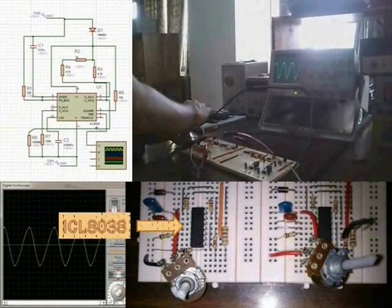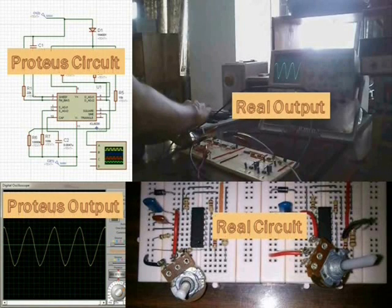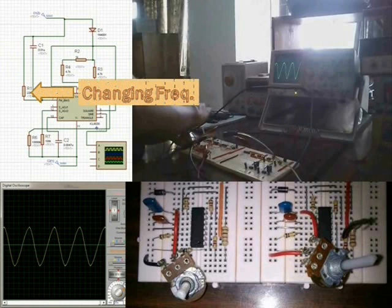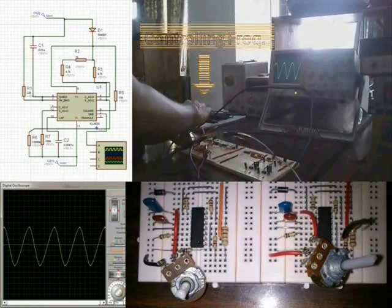We used ICL 8038 to produce the sine wave. Initially we designed Colpitts and Wien bridge oscillators, but they don't operate well at the low frequency range of 300 to 3400 Hz. So we opted for that IC. Besides, it offers the opportunity of changing the frequency range, which was not available with those designs. The 10K pot connected between pin 8 and VCC plus 12 volts mainly controls the frequency.